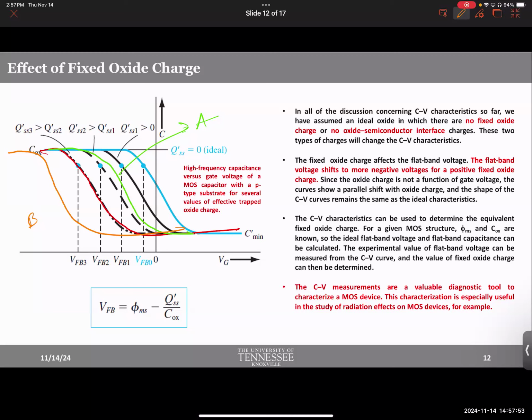So you have air, which is an insulator. We don't always get the thunderbolt because you have an insulator. You have a huge charge piling up at the clouds, and you have ground literally at ground. But if the voltage exceeds a certain level, the insulator can break down. So you see, you have a direct connection from clouds to the ground, which you don't like. Similarly, the gate oxide is there to stop you from letting current flow from gate to the semiconductor. There is an oxide there so that current cannot flow from the gate all the way to the channel. But if the oxide breaks down, the device will be destroyed, as you can see.